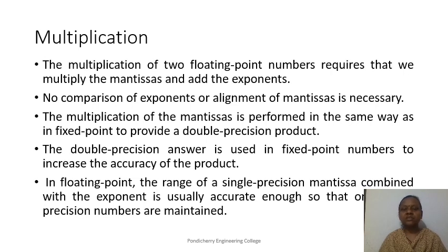If you take some n bit register, the multiplicand and multiplier are n bit numbers, the product can be twice that size, so it can be 2n. We have seen that the A as well as the Q register both will be holding the product after multiplication in case of fixed point numbers or sign magnitude numbers.